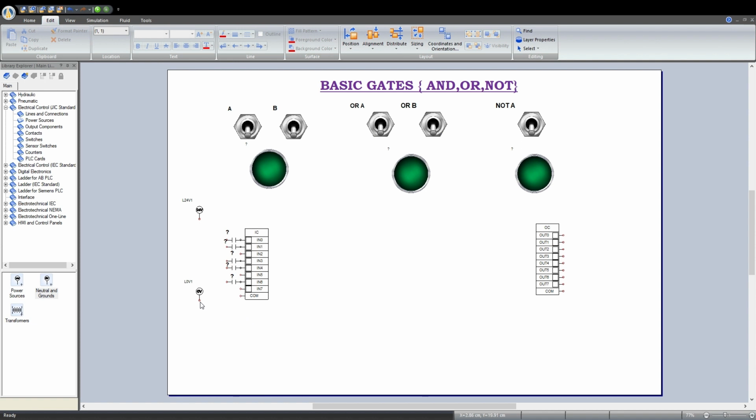Note that the 0 volts should be connected to the COM port, and all the connections to 24 volts. Make sure that all the connections are given correctly without any misplacement.